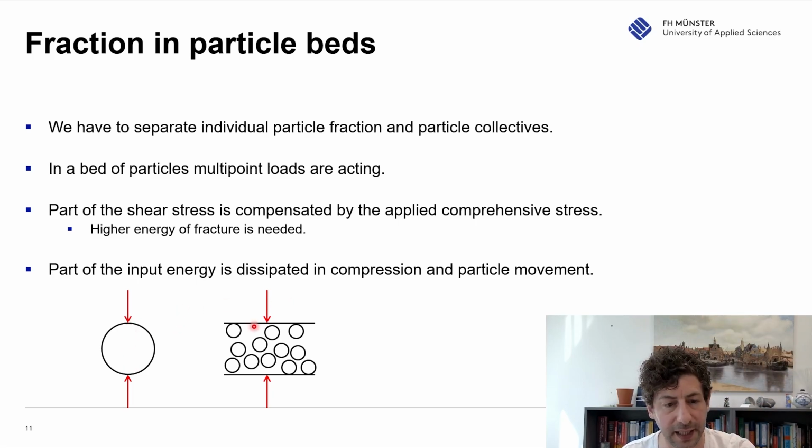And the particles, when they are compressed, are also pressing against each other. So this particle will not only feel the force from the top and the bottom, but also from the left and the right, right? So in the bed of particles, multi-point loads are acting. And then part of the shear stress is compensated by applied compressive stress. Higher energy to fracture is needed.